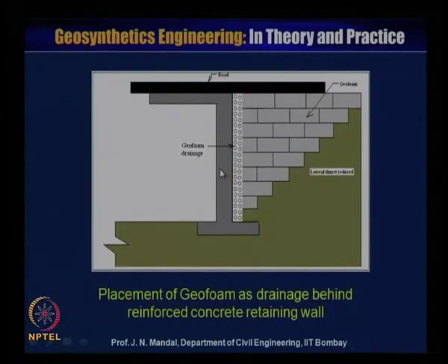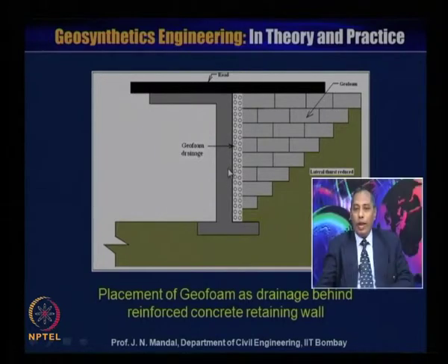Now this is the placement of geofoam as a drainage behind the reinforced concrete retaining wall. So you can provide the drainage material. I showed you what the drainage material will be. So you can simply provide the drainage material and then the geofoam. This geofoam will act as a drainage, as well as a compressible inclusion.